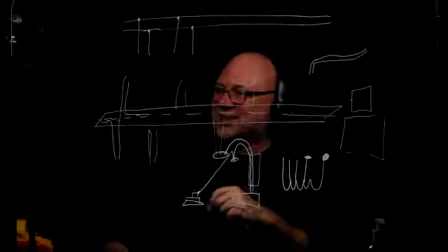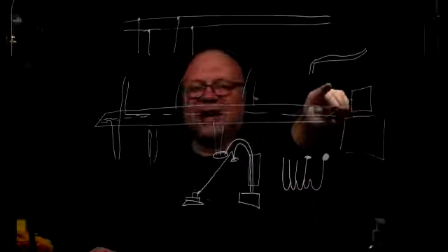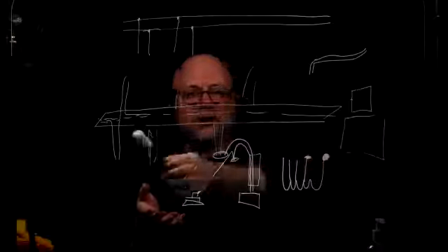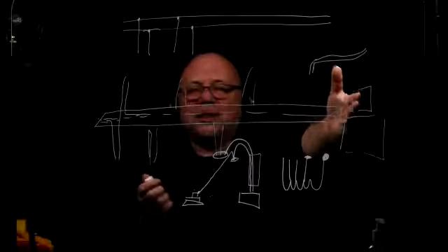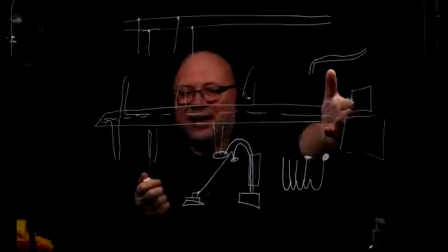All right, 100 speakers. Now if we tap the speakers at 2 watts each, and this is a 100-watt amplifier, how many speakers are going to be able to plug into the whole system before we run out of power? 50. There we go. Another advantage of using that distributed audio system is that you just look at what the power capability of the amplifier is, and you just add the taps. Make sure you don't go over.